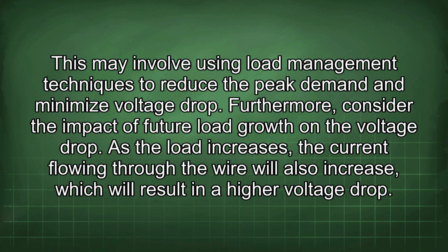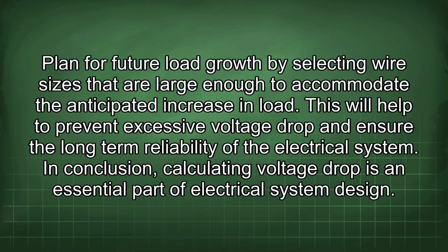Furthermore, consider the impact of future load growth and the voltage drop. As the load increases, the current flowing through the wire will also increase, which will result in a higher voltage drop. Plan for future load growth by selecting wire sizes that are large enough to accommodate the anticipated increase in load. This will help to prevent excessive voltage drop and ensure the long-term reliability of the electrical system.